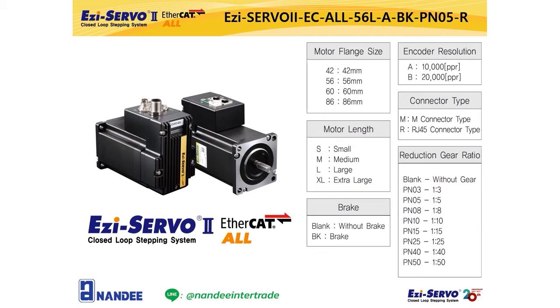You can select the motor from a NEMA 17, 42 mm size motor to a NEMA 34, 86 mm size motor. The length you can select depends on the motor size. The encoder resolution can also be selected as shown in the table. R means RJ45 connector type. There are 2 types of connectors, M connector and RJ45 connector. Gearbox and brake specifications are also available.